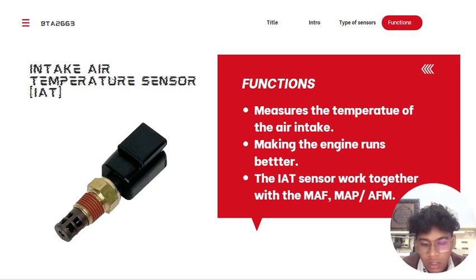And then, as usual, the resistance is measured and converted into a useful signal for the ECU. The IAT sensor is often integrated into the MAF or the AFM. If it's not there, you can usually find it somewhere in the intake, usually near the throttle body.